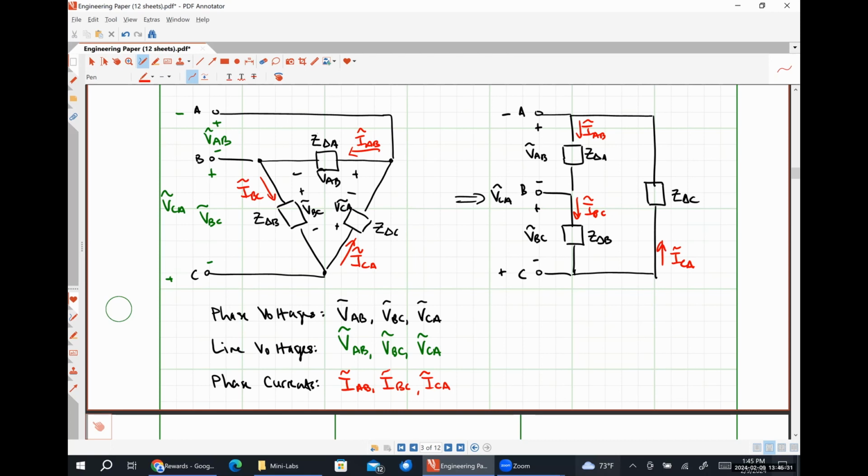Most transformers, if you're using that as your voltage source, are going to have what's called a star configuration, which is really just a fancy word for a Y configuration, and you're guaranteed to have a neutral conductor. Loads are an entirely different bag of cats, right? So you may have access to a neutral terminal, you may not have access to a neutral terminal.